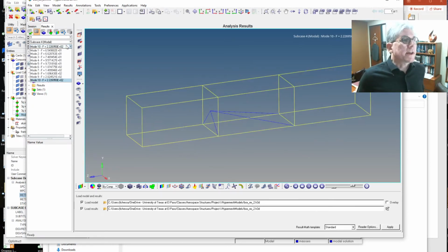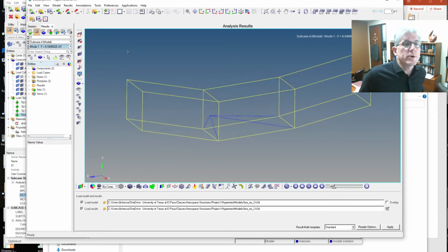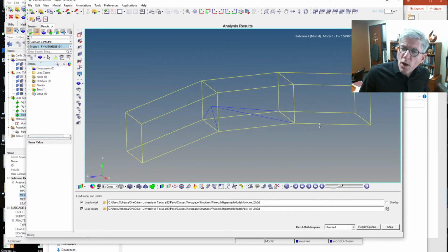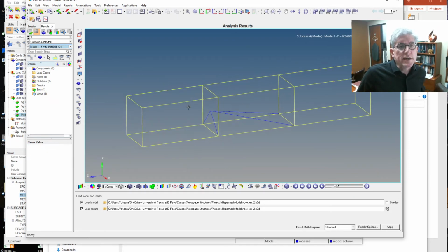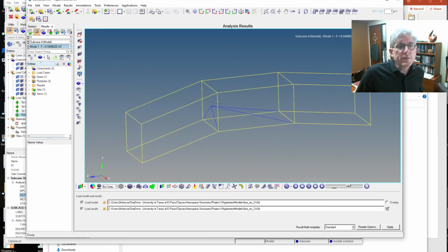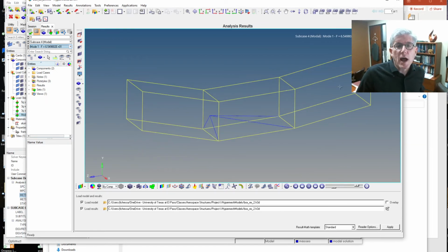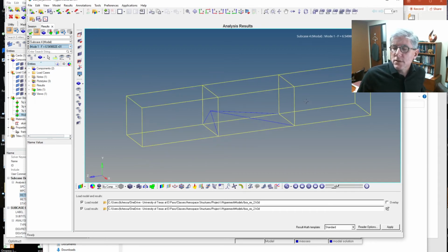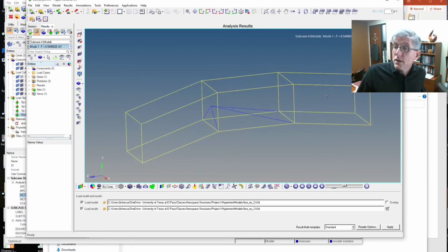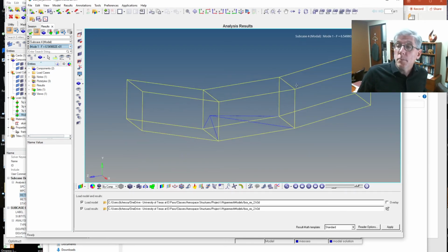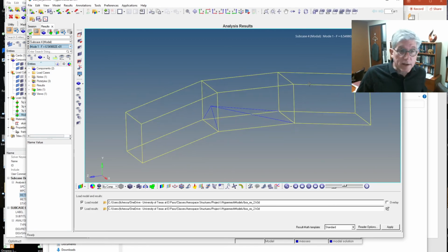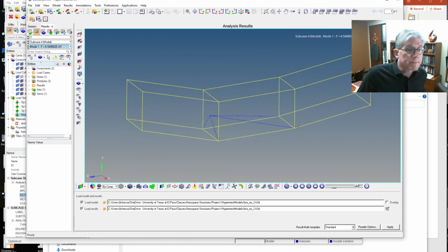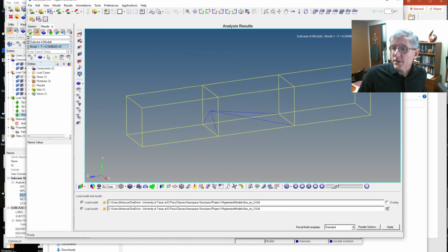So as I was saying in class, if we look at this first mode here, it's a bending one. So if we want to stiffen up the structure, one thing I might be tempted to do is stiffen up these top and bottom frame elements, maybe make them a bigger I, like a different section, right? And then see what happens, okay? All right. I think that's enough for that. We'll stop.